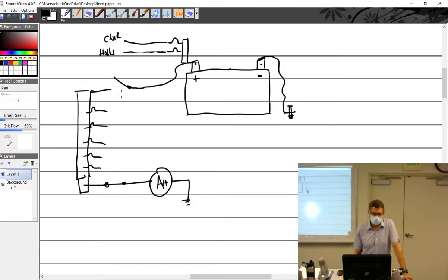All right, so when the master is closed and the alternator is not operating, we'll just do this to indicate not operating, and all of these loads are going out, the battery is being discharged. And it's going out to all of my loads. And oh, by the way, we'll just put a little ammeter right here. Ammeter. Ammeters are connected how? Series. So does that mean I got to put an ammeter right here and I got to run everything through the ammeter? No. What do I do?